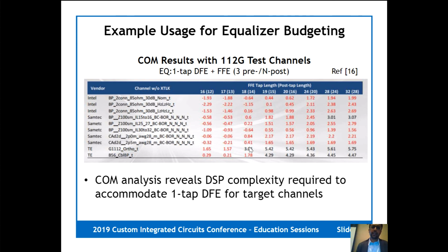So they're not floating point. Sorry, the question was: are the FFE taps ideal, or is there any other limitation? There are some quantization limits applied on the FFE taps themselves, but they're not the ones that are limiting the tap benefit. I think the bigger limit comes from the ADC resolution and the DAC resolution.